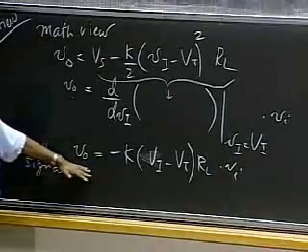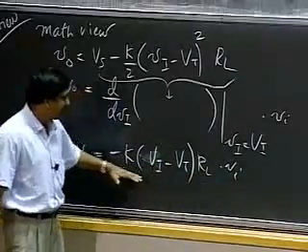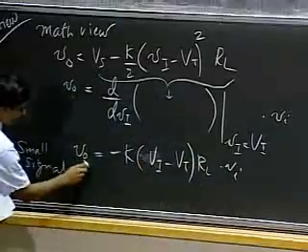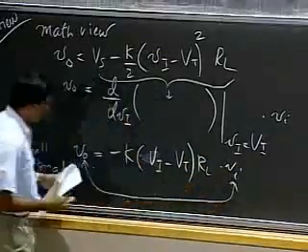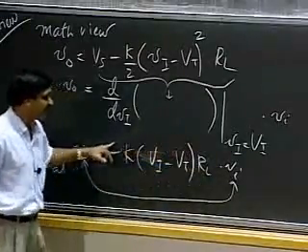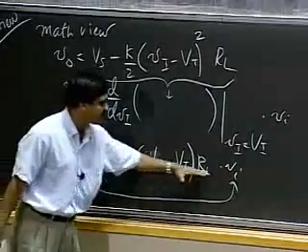So my small signal output was some function given by K Vi minus Vt RL times small Vi. And notice that this is how Vi relates to VO. And this is a constant with respect to Vi. V capital I is a DC bias. So this is a constant.